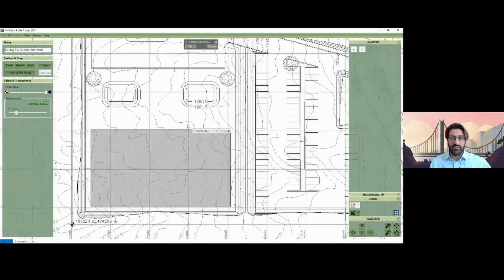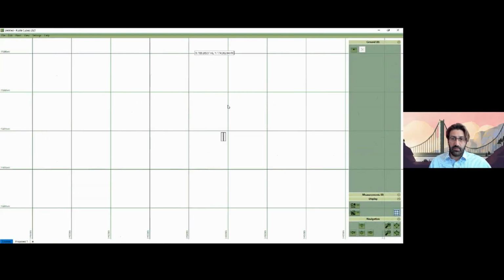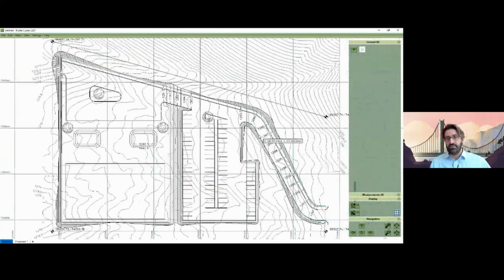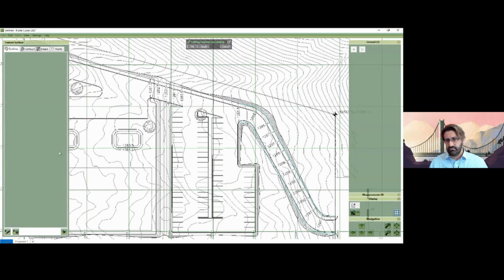So it works in very much the same way as the PDF does. So say if we want to remove a color, we can just click on that. So it's basically as simple as that. You have your CAD file as an underlay in your project. On top of that, you'll be used to adding a feature surface, so taking off your existing, and you might have, in the past, gone to here and clicked here and then browsed to try and find a CAD file. Well, now there's this other option where you can actually extract directly from embedded files, because the CAD file is embedded.